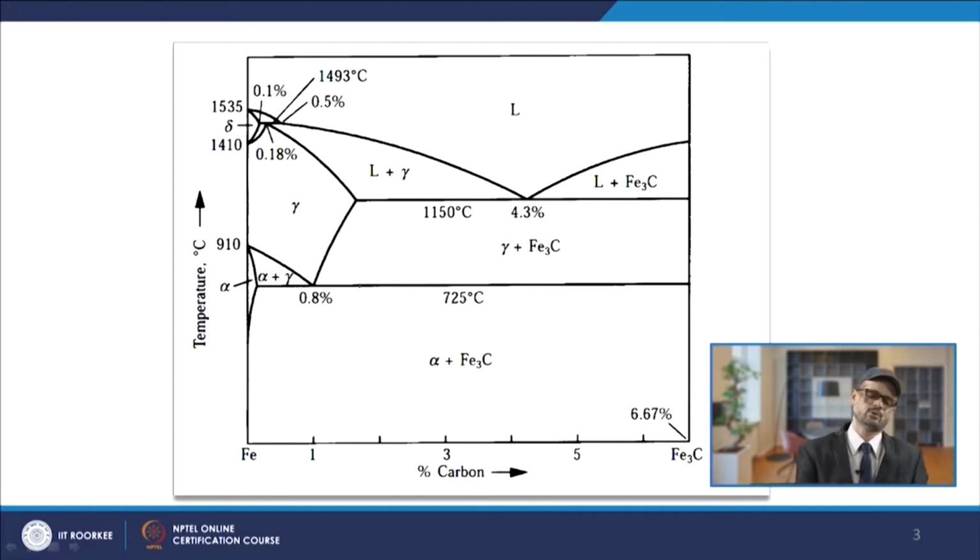So, first of all, when we combine the iron with carbon, up to suppose say 2%, below 2% we call it steel or carbon steel. In that, basically you have low carbon steel, medium carbon steel or high carbon steel. So, it will go maximum to 1.5% to 2% for the steel. Once the carbon percentage moves from here onwards, then we call it cast iron.